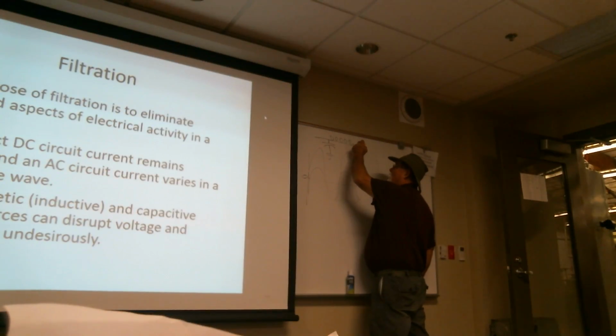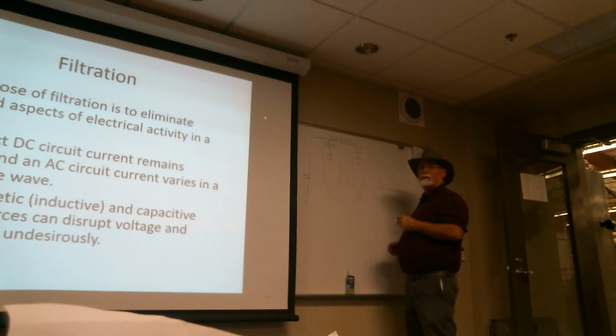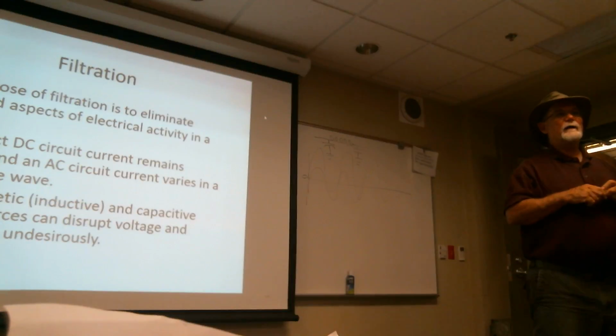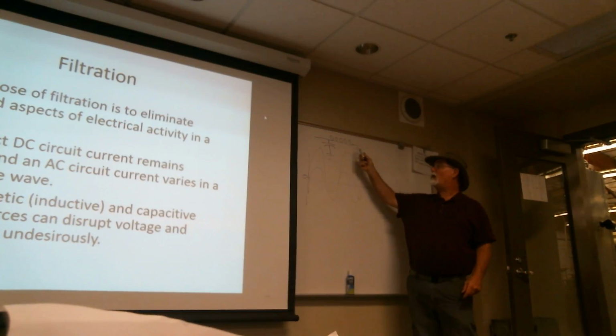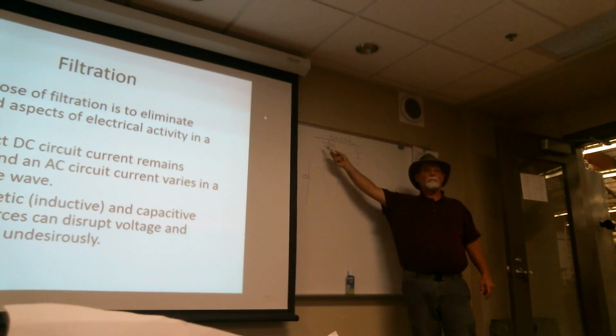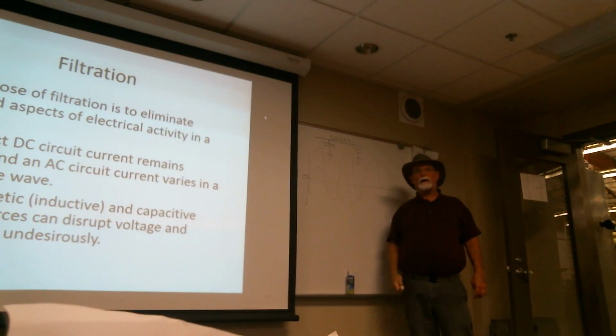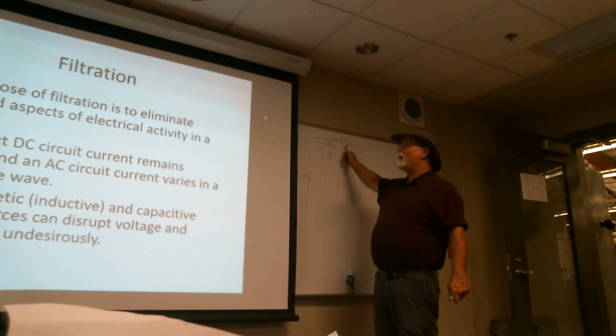In fact, I could do it a couple of ways. I could double pass filter it. Do that on both sides. So anything that's left over here, it also gets shunted to ground. Okay? The DC portion can't go across because those are just open for DC, right? Okay? Very common to see this kind of thing.